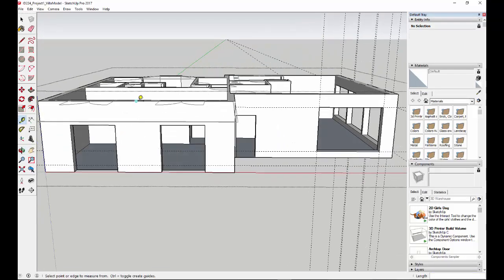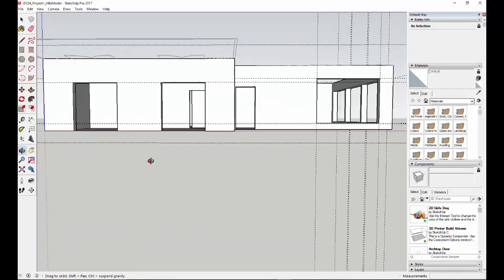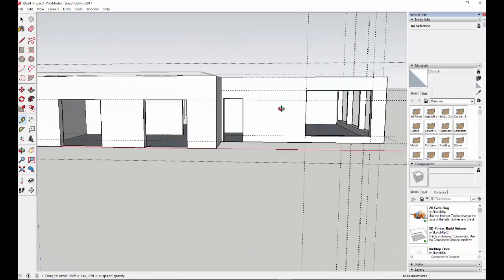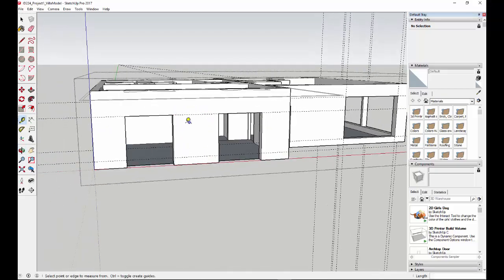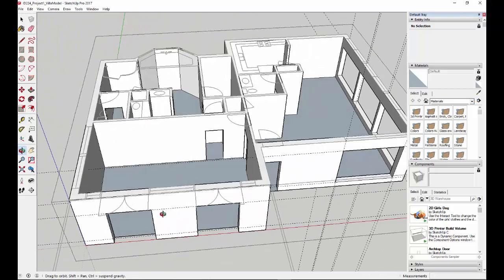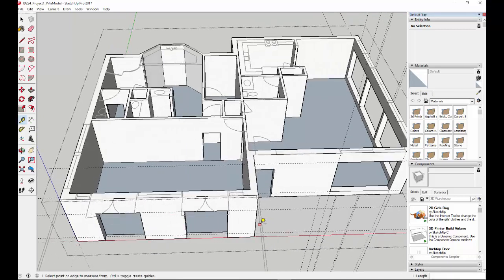This time I'm going to go from the top and I'm going to match where the doorway line is, and we're going to have a guideline just like that. There we go. So you can see that they're not quite as tall as these walls over here, but they are matching the geometry of our room very well. And I'm going to look at the very top again, and I'm going to pull from the right edge, snap it there, pull from this guide, snap it there. Same thing over here, pull and snap.